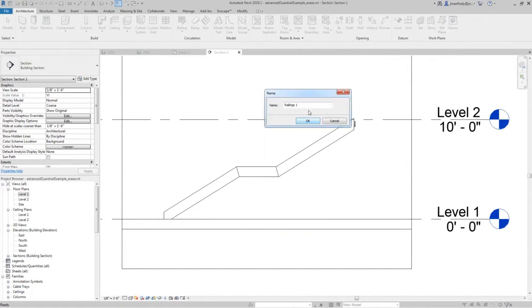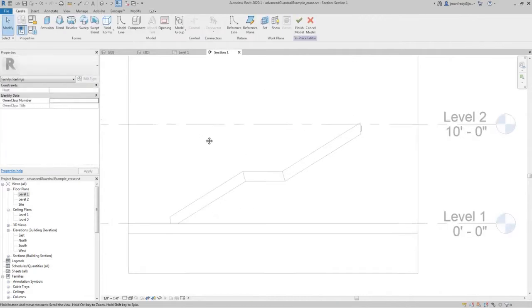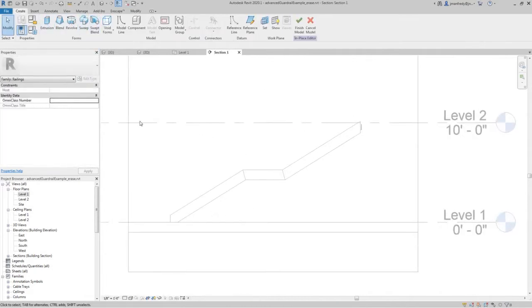So call it whatever you like. So with the tools that are available, what I first want to do, which I find easiest, is to draw a profile, like a wall or something, whose edges describe where the railing will follow. It'll become the path I'm using to draw the railing, and the railing is going to be attached to this invisible wall. So walls are extrusions.